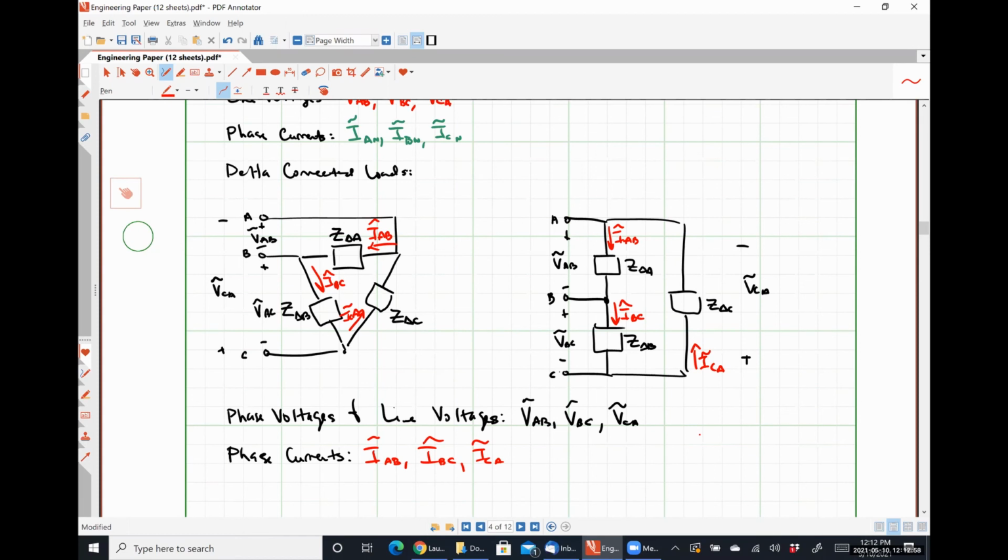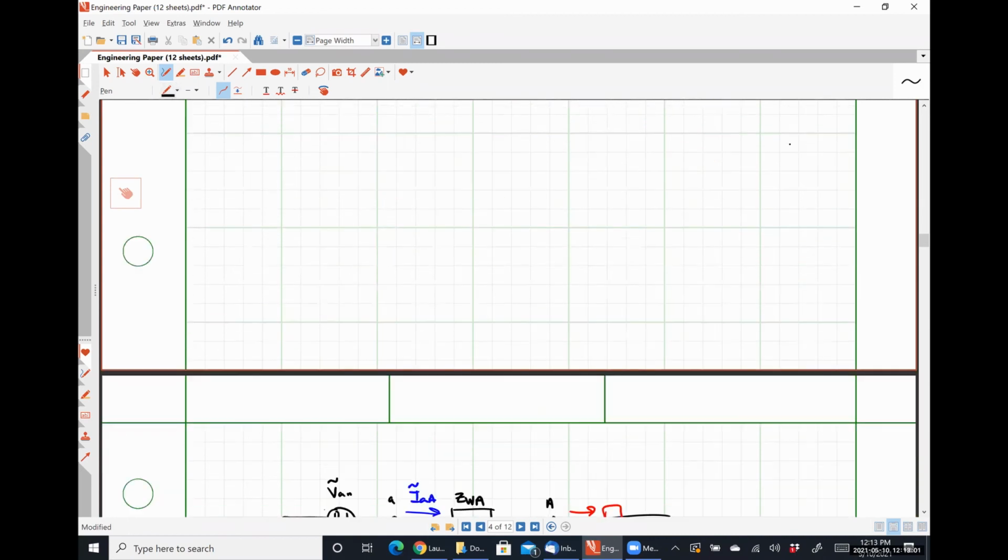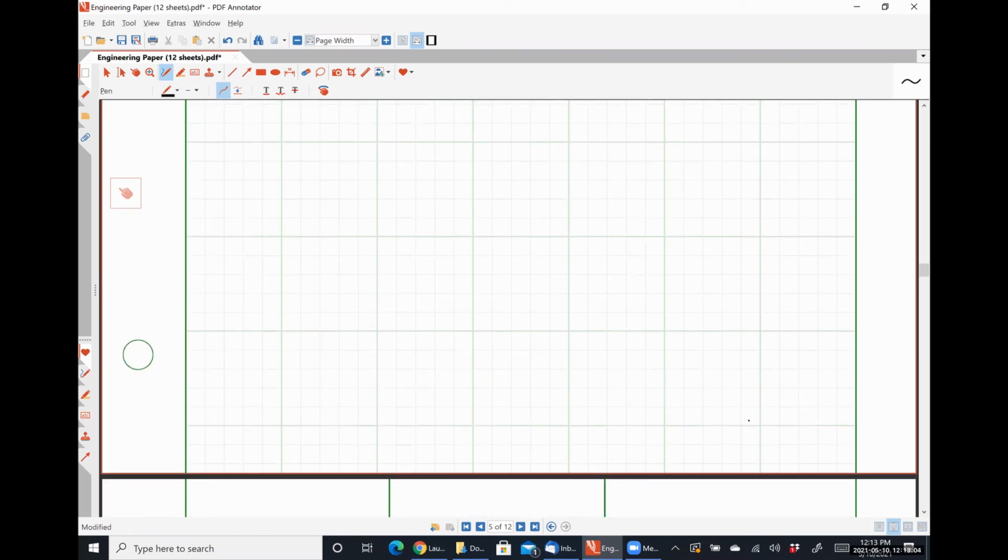And so what I mean by that is, this is just a quick aside. Let's look at a DC circuit. I have 5 volts in parallel with 4 volts in parallel with a 10 ohm resistor. What's the voltage drop over my resistor? The correct answer is beats the hell out of me, okay? If you have 2 different voltages in parallel with each other, circuit theory breaks down.